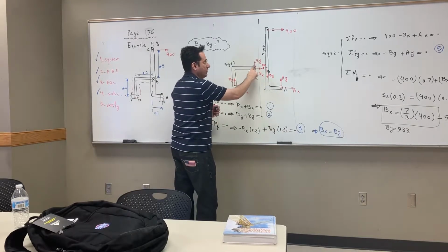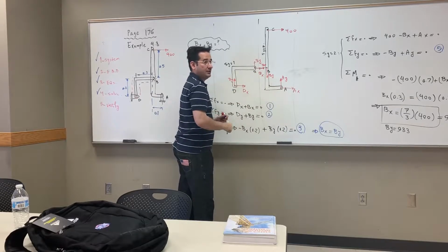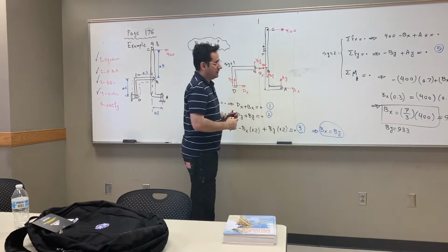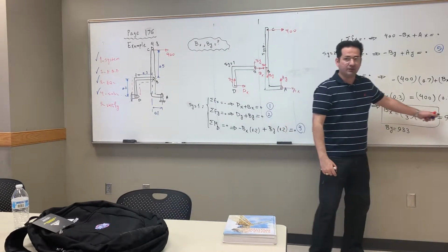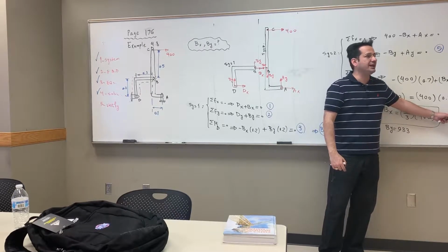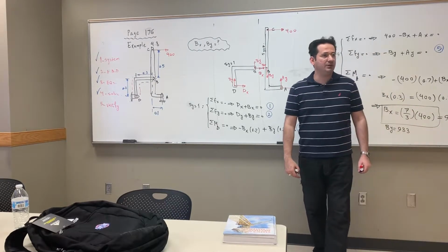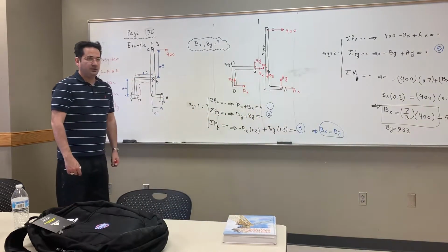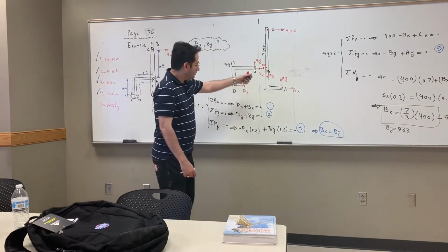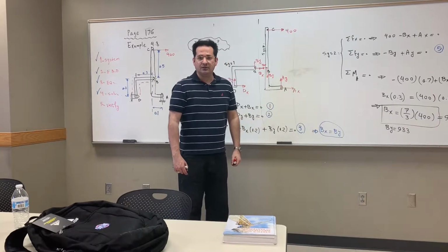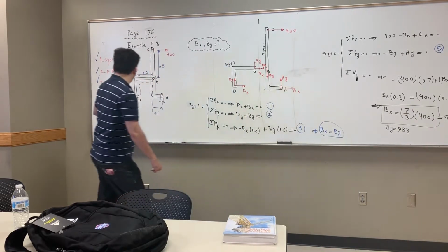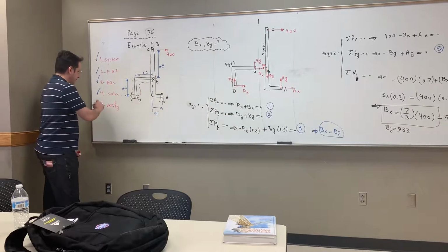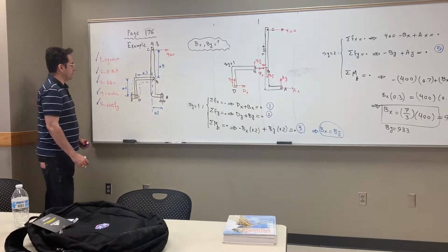Maybe not sure about By, but Bx must certainly be positive. Now you look at the value, it's positive 933. If you had a negative, that would be terribly wrong, and you should go and reconsider where you messed up the sign or directions. So that's a step to verify. Now we verified and it looks right, that example is right.